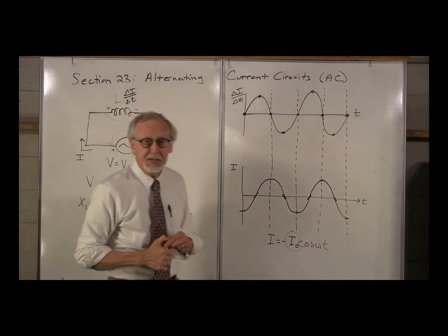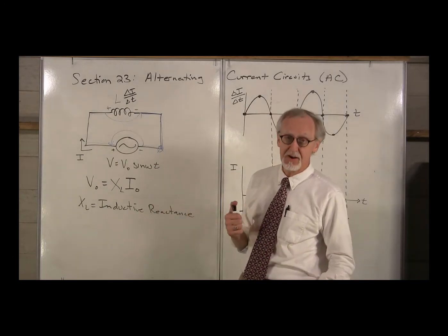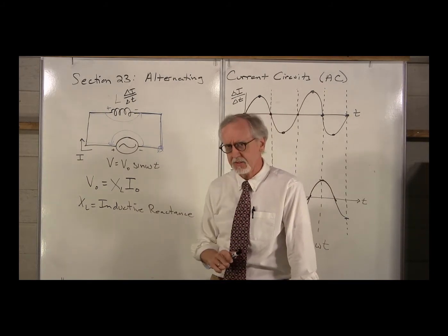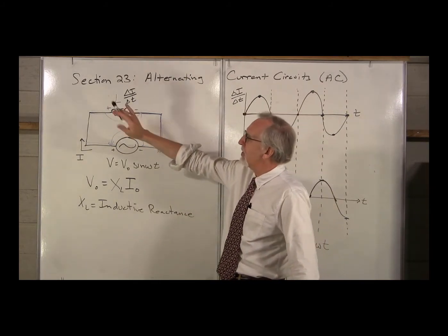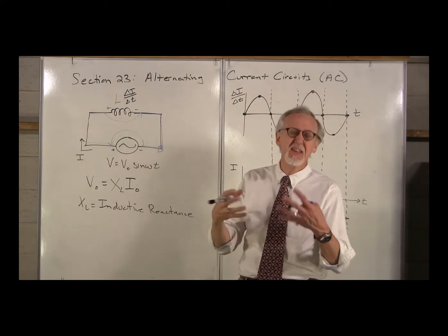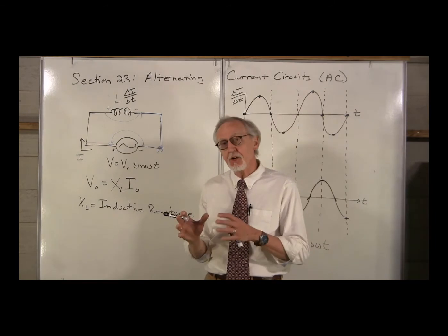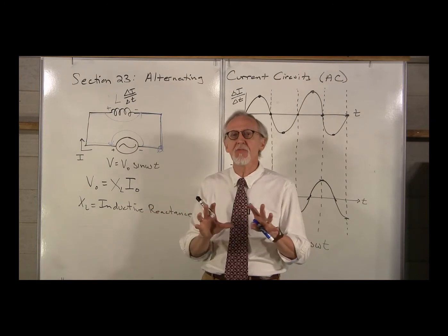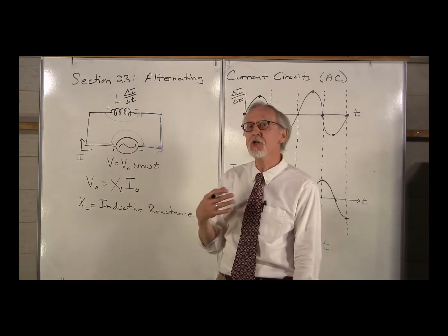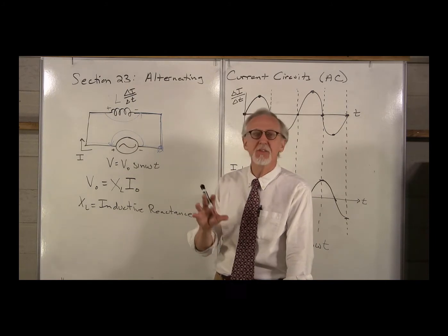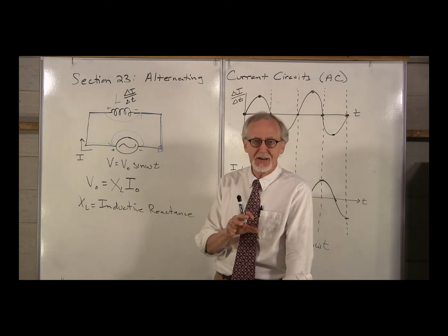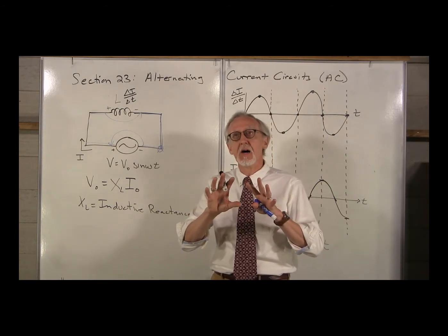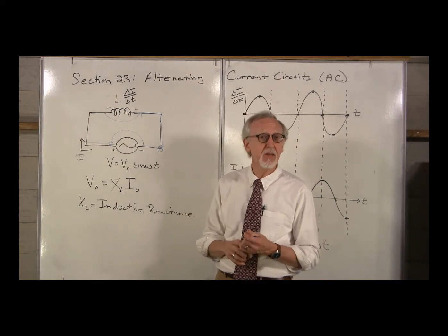Let's see if we can use some physical arguments about an inductor and figure out what sorts of things might affect the inductive reactance. First, let's remember what L was. L told us the strength, so to speak, of the inductor. And the inductor resisted, and I use that term very loosely, any change in the current. I said that it was kind of like an inertia for the current. The more inertia the circuit has, the more it tries to stay the same, the more it tries to reduce any changes in the current.